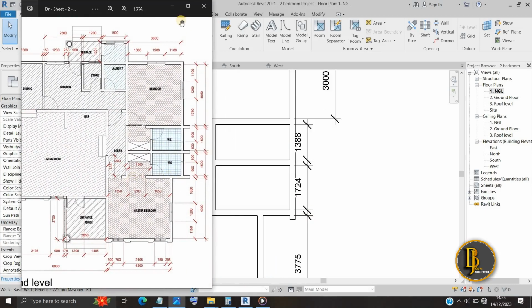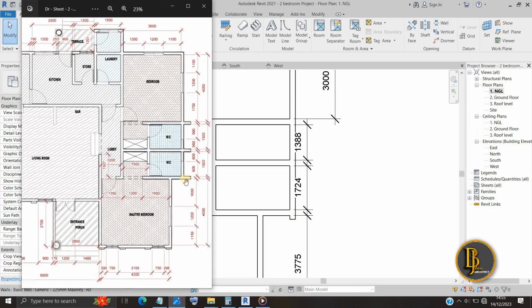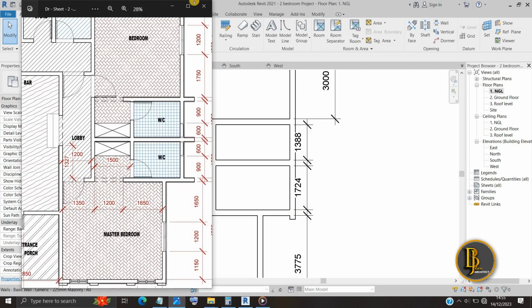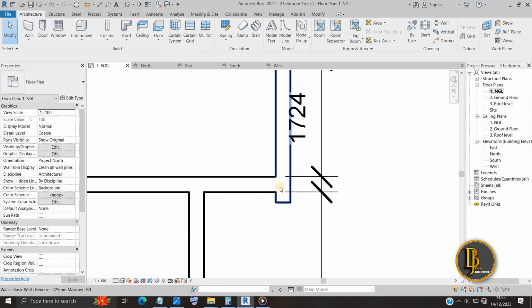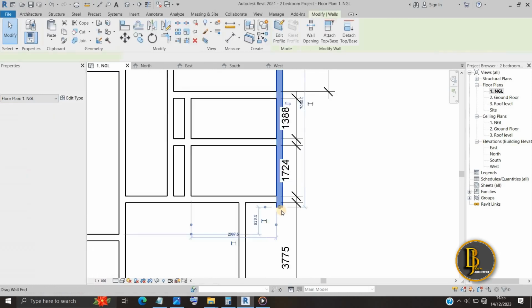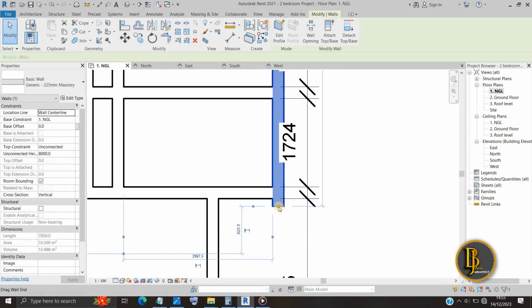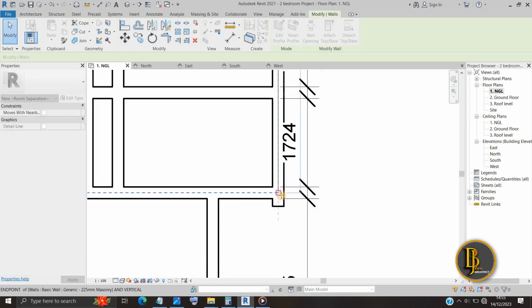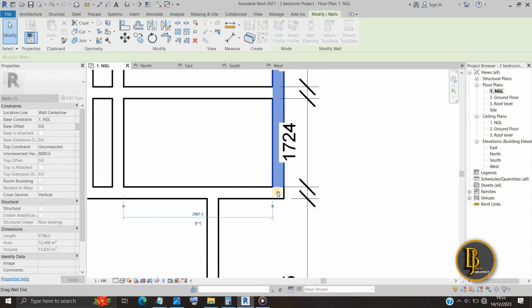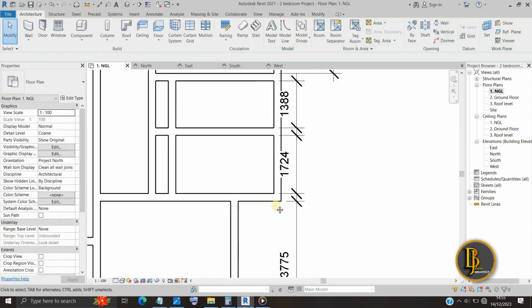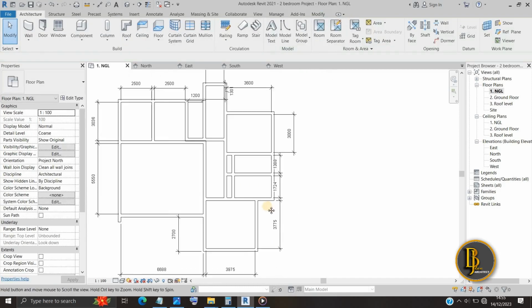So if you notice, this wall is not coming out here. There is no wall coming outside here. So this is not supposed to be there. So what you can do is hold your left click button, then drag it up a bit. Once you see that box you are seeing here, you drop it, release to edit that place. So that's looking good now.